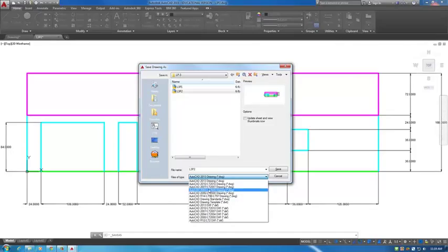The other type of file extension I want to talk about is a DXF. A DXF is kind of an industrial exchange file format. It's kind of the general go-to file format to use in machines like CNC mills or lathes, CNC meaning computer numerical control. Also, it's used for our 3D printers in the lab. Also used to import into CorelDRAW for our Epilog laser. So, like I said, it's a very